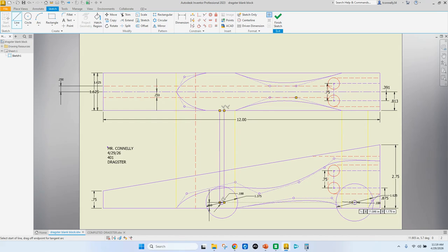I'm going to do the same for the back wheel now. So I'm starting with the axle holes. When my axle holes go in, I do want to make sure that they're probably on either a flat spot like this, or if you got a big curve, you want it on the fattest or furthest point. Right? So now we need to put in our axle holes in the top view. So I'm just going to go back in my green dot, and I'm going to just extend these lines. The reason I did these separately is because we have construction lines, and then we're going to have hidden lines.